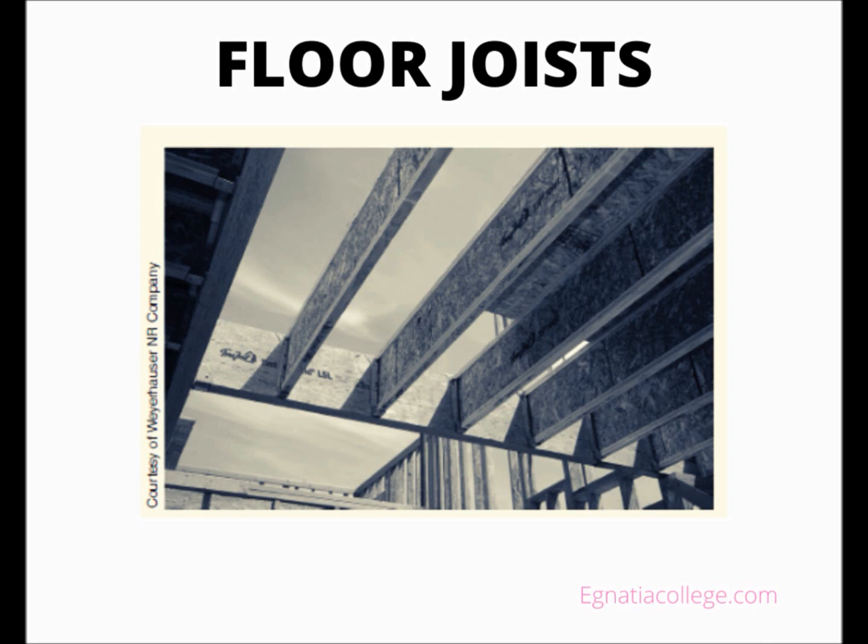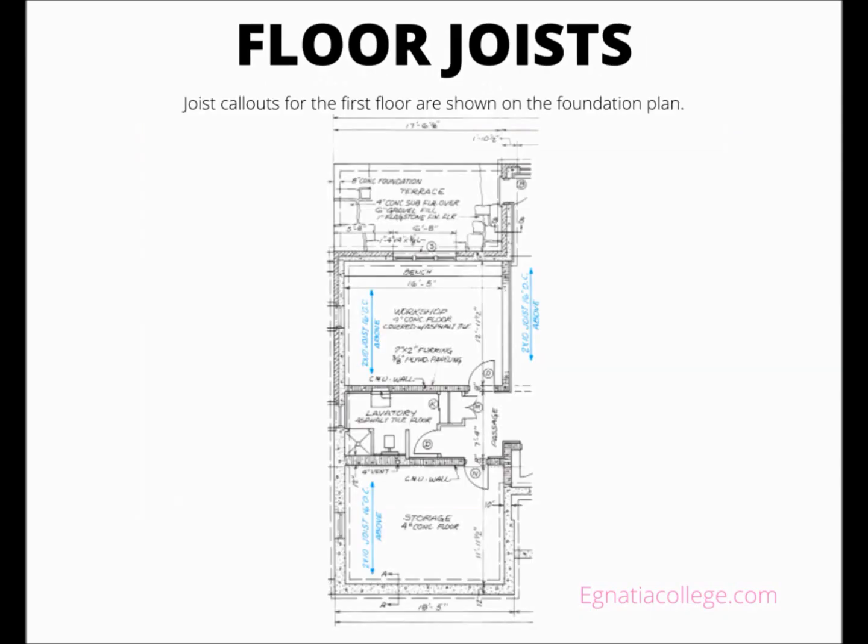I-joists are often called TJIs because the first I-joists, introduced over 40 years ago, were named after the Truss Joist Institute, which developed the first I-joists. Although the materials in each type are different, their use is essentially the same. The joist header in each case is of similar material to the joist. When I-joists are used, the header is typically an engineered rim board that is manufactured to have the same depth